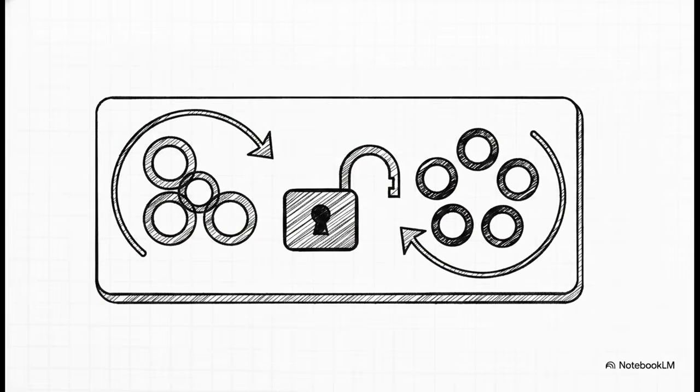But what if the part's physical function doesn't actually require those distinct patterns to be locked perfectly together? If that interrelationship just isn't necessary, the designer must explicitly break the simultaneous requirement by placing the notation SEP REQT, which simply stands for separate requirement, right next to each applicable feature control frame. This is a game changer because it frees up the inspector to optimize the setup for each pattern independently, potentially saving parts that are totally functional but might have failed a strict simultaneous inspection.